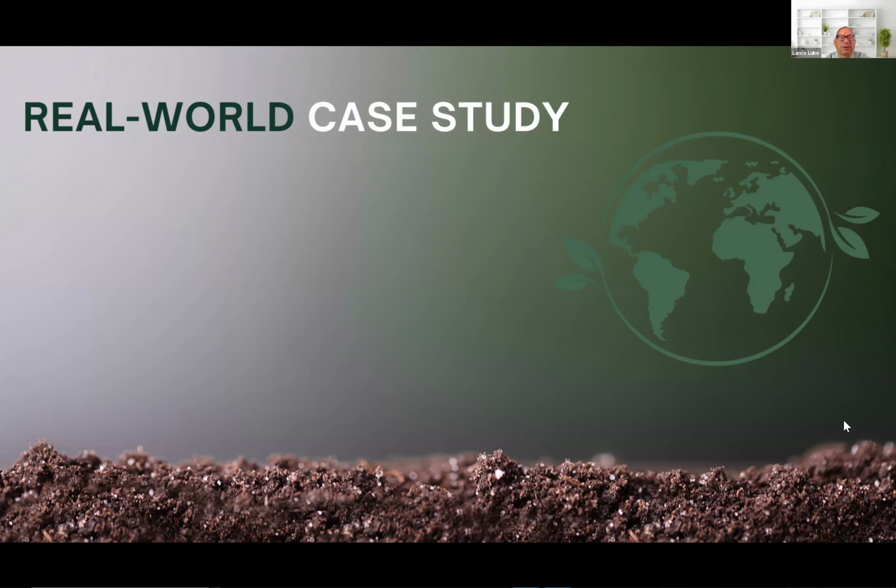Now, here's another one that had to do with a single family house. A brand new house was built in Kaimaki, and the walls were CMU block, and the house was settling. They had drywall cracks, cracks in the CMU blocks where the grout joint was, cracks in the ceiling drywall, and even in the concrete slab. I was hired as an expert witness on that case because the homeowner was suing the contractor.